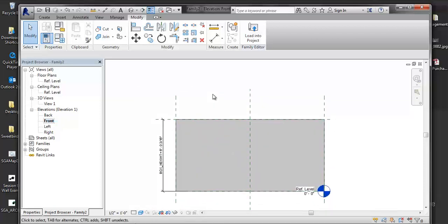So let me look at my notes here. Pause this. Very, very important. Very, very important. If I come into another view, all of a sudden, and I've made this mistake too, it's like, well, wait a minute, I thought I constrained that. Why am I seeing it, right? Not realizing that all I have to do is constrain it in one view, and it's a global constraint. It's not a regional constraint.